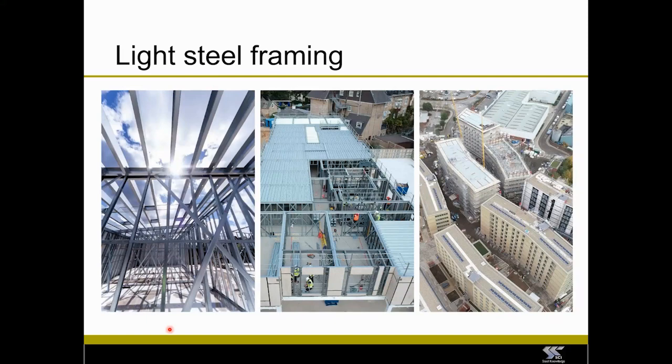And some light steel, I think in this case they're actually roof joists rather than floor joists, but very similar application. The next image shows decking being placed on light steel walls, so obviously there's going to be a composite slab floor in this particular development. We can also see some sheathing board being placed on the external walls of this light steel frame as well. And we'll talk about boards a bit more later on as well.